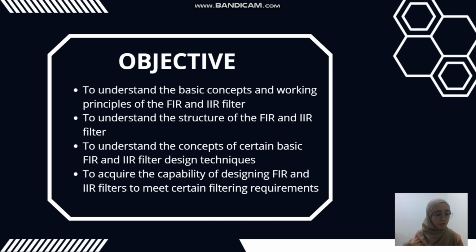So the main objective of a FIR filter is to implement a linear time invariant system with a finite number of coefficients for application requiring a linear phase response. While for the IIR filter, it is to implement a linear time invariant system with an infinite number of coefficients for application requiring a sharp cut-off step roll-off in the frequency response. So that's the objective for our assignment.